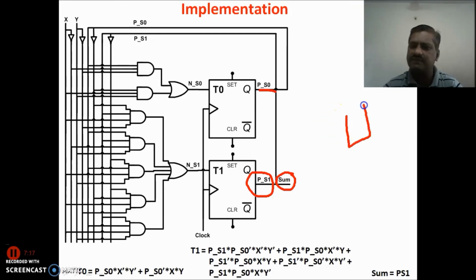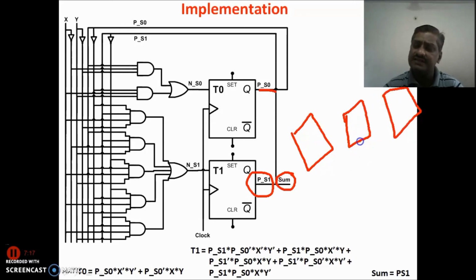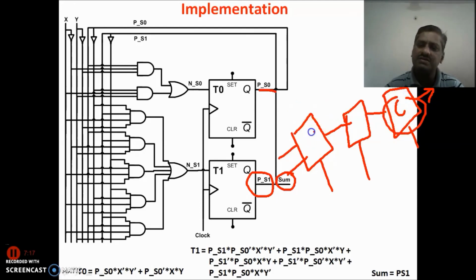This is always the format for any digital system design. If we are going for a synchronous sequential circuit design or any sequential circuit design, the format is always something like this. These are the states. This is the input combinational circuit, this is the output combinational circuit. Here may be the input, this is a combinational circuit, and here may be the state. Again, this is a combinational circuit, and here will be the output. This is optional sometimes, and in some cases both are needed.